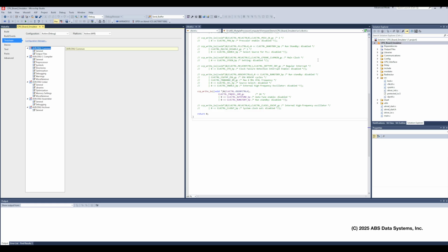I can set breakpoints and force triggers to my oscilloscope or logic analyzer so I can capture different views of what might be going on in the hardware. This also gives me the ability to single step through the code. I think this will be very important when I go through the code and debug the JLink interface in the programmer.